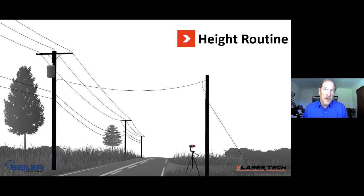And mostly because the poles are predominantly nice and vertical, straight up and down, with a flat surface there. So the first shot you take is a horizontal distance. If the base of the pole is obscured, or even other parts of it, you just find a clear spot where you can see the pole and you shoot it there. It'll measure both the distance and inclination and calculate that HD for you. So anywhere on the pole is good for that shot.